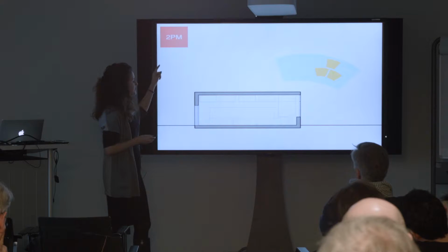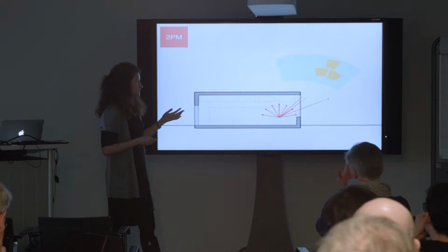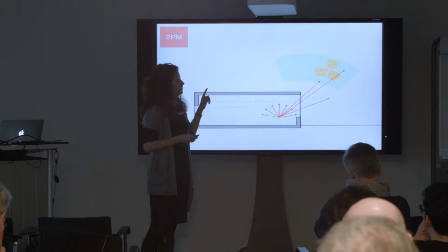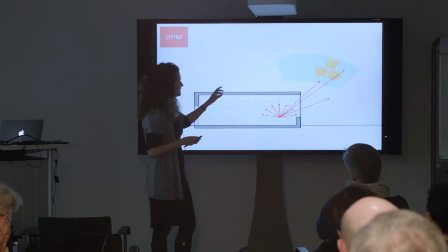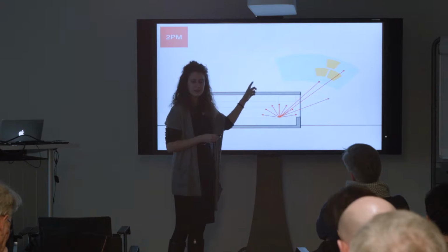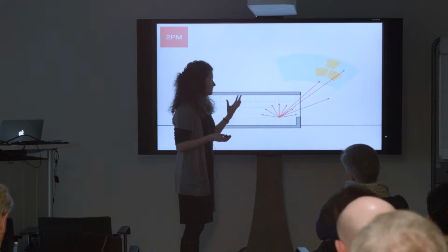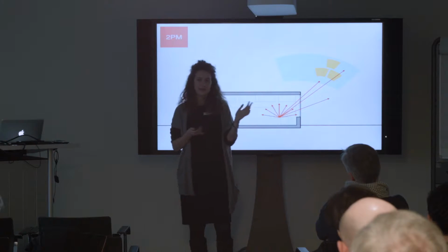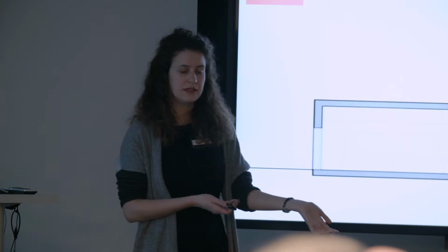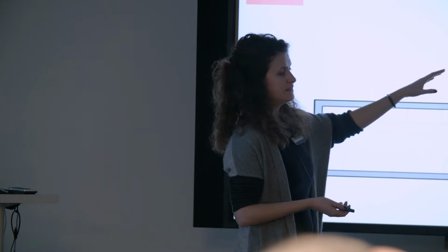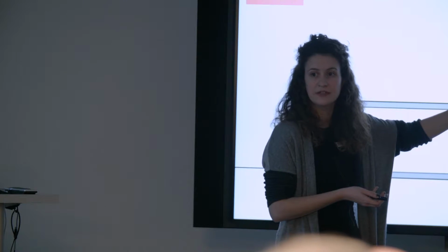This has dramatically changed with the 2-phase method, so the first rcontrib. Here the sky definition completely changed. We don't have multiple sampling runs for each patch or each sky, but we simulate everything, all the sky vault and all patches, all at once. But there is an assumption that the whole sky vault, sun and skylight, is treated in exactly the same way. So it's assigned a glow material, so it's a stochastically determined simulation, and the sky luminance is not at a point anymore, but it's spread over 3 patches, which are the nearest ones to the sun location at that time.